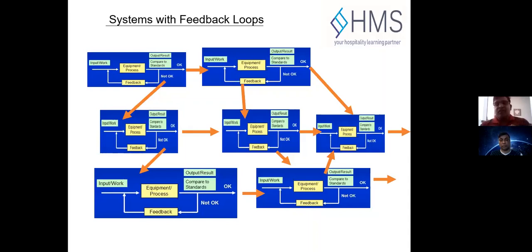And then, so this is very technical, okay, which as an engineering manager and engineer in charge, you need to know if one system doesn't perform, what will be the effect to the service, and which area will be affected in the building, and what will be the services affected, and how you're going to monitor it, how you're going to tackle it, what areas need to be isolated, what areas need to have the alternative for that. So this is one typical system loop which you can see is multi-dimensional.